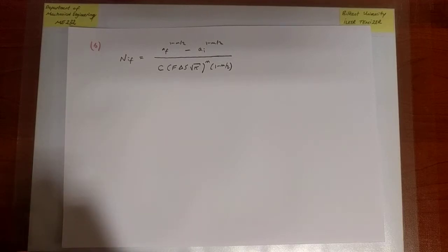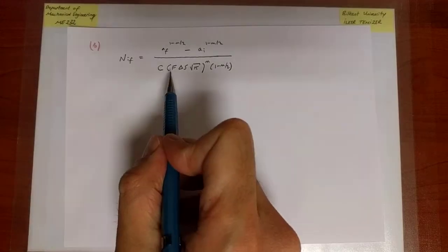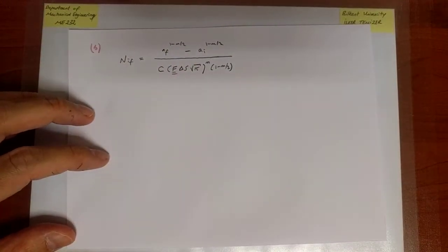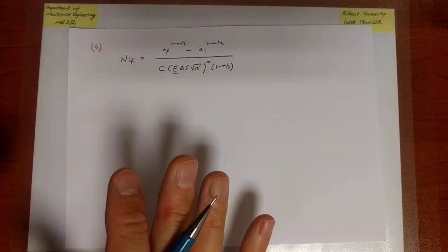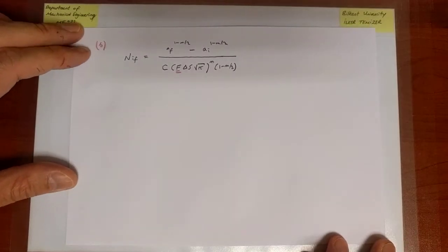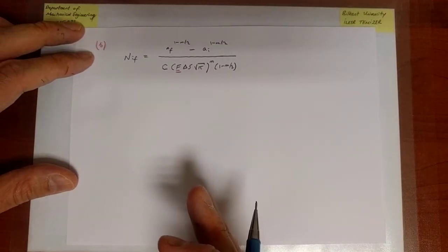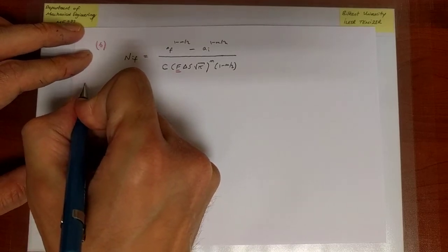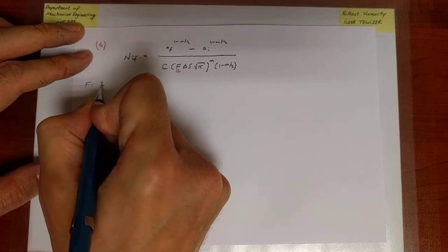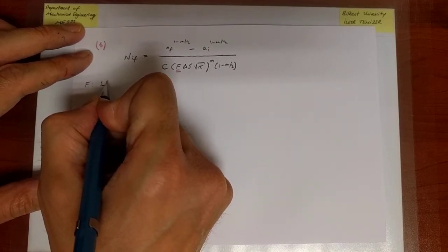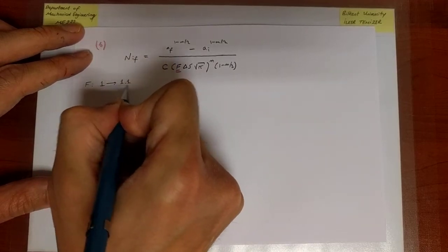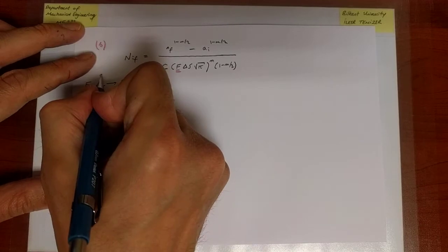Now, let's get one thing out of the way: F. And the way we're going to look at this is very pragmatic. It's not a big deal. What I'm about to do is give you the sort of argument that we find in the book. It's a back of the envelope calculation. So what we know presently is, that's why I told you the value of F, it starts with 1 when the crack is very small, or very, very close to 1, and it grows to 1.1 at the critical crack size.